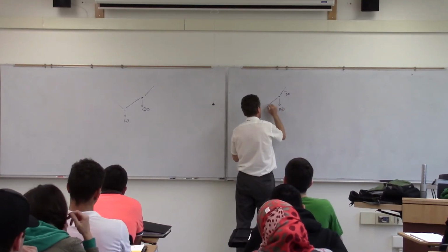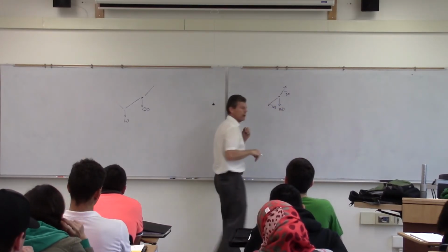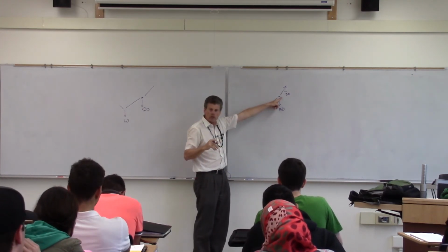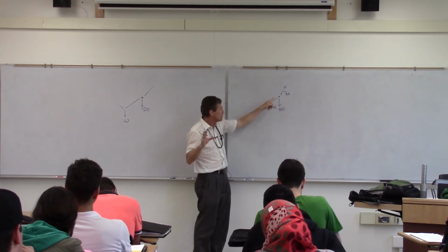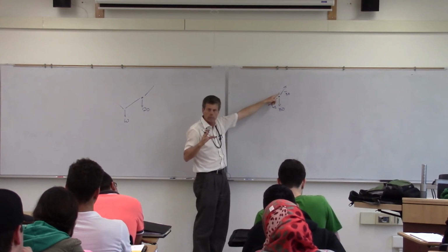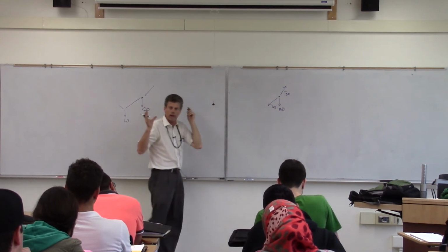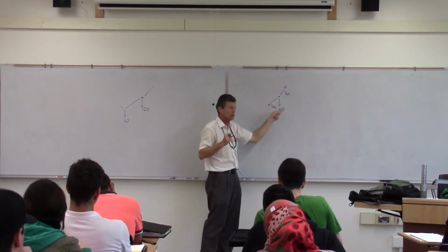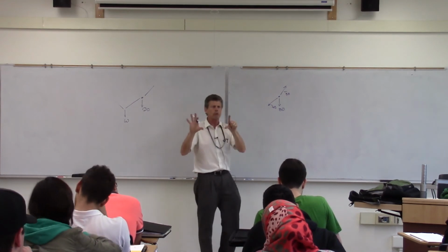45? Okay. So basically, if you look at just that single point there, you have two unknowns, right? So you can solve for that. Sum of forces x, sum of forces y, you're all done. Or you can do force triangles. I put both of the solutions on.